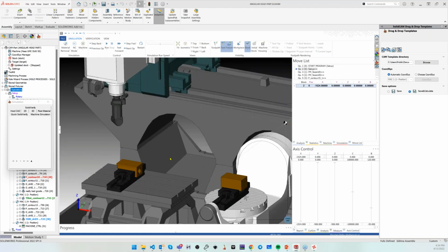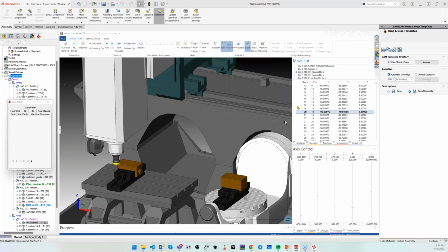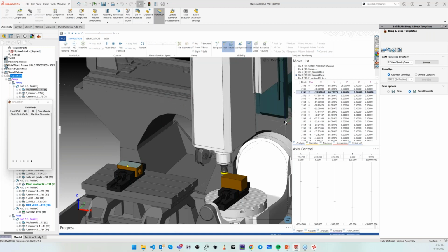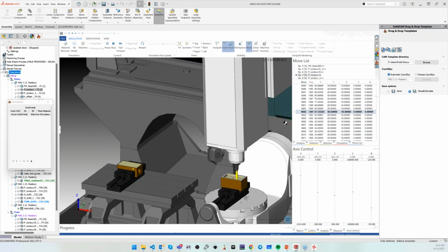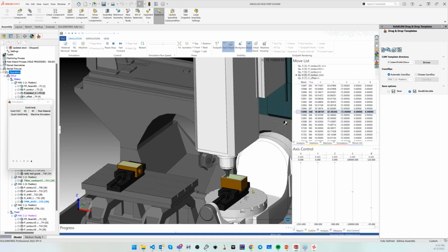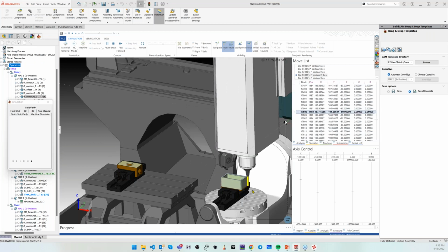And what is unique in SolidCAM here is that you can manage the tool changes to save tool change time without changing technology. You can just see how it looks in simulation. I'm working with the face mill. Once I finish the work here, I switch to the second part and come back to the first part. So you see how the spindle is jumping from table to table just to save tool change times.